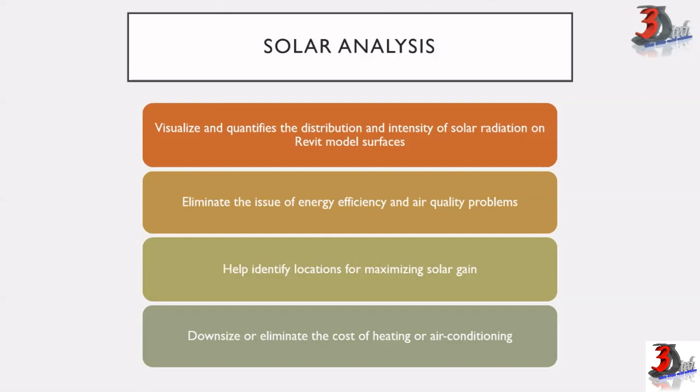Okay. So this tool provides automated settings for specific study types as well as customizable options. Solar analysis uses surfaces on the model and a surface can be created from standard architecture elements. For example, we have our wall, roof, floor and ceiling, or even if you have only conceptual meshes.